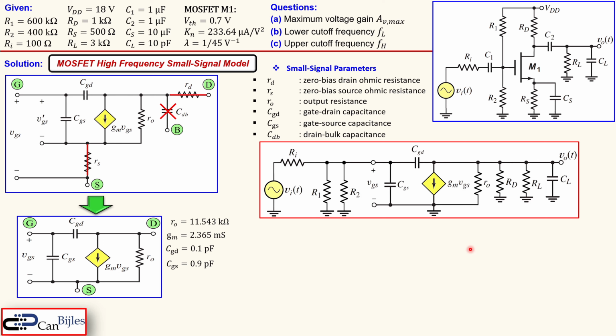So how do we proceed in this case? Well, you can again apply the theory for the circuits and then come to the transfer function from the VO or VI. But we can use an approximation. First designate the gate nodes, drain, and the source node. Well, we can also use the approximation we call the Miller's approximation. It's not an exact, but it's an approximation which will allow us to do the calculations much faster.